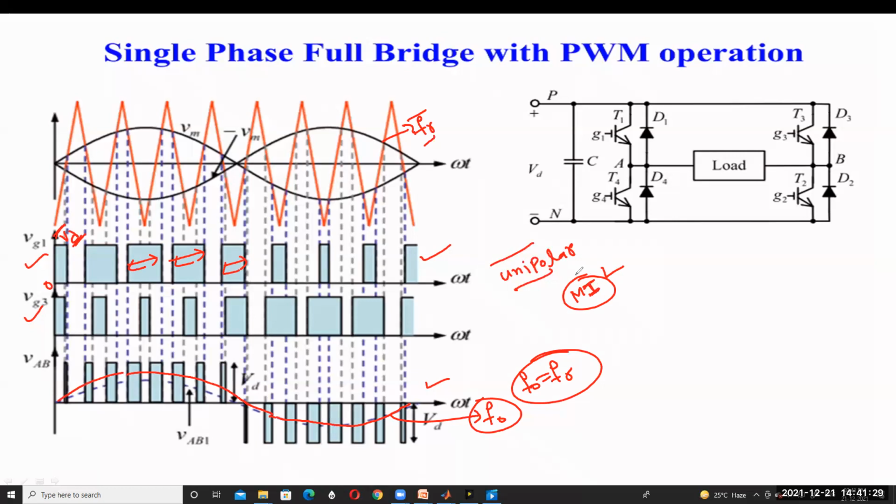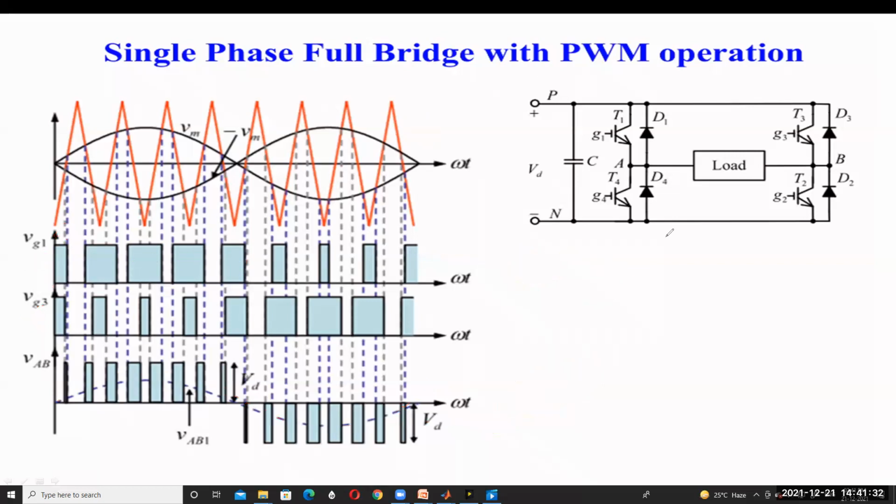So in this design of the inverter, we need one voltage source, VDC. Different types of components are required for designing the inverter in MATLAB. First is the VDC, then the MOSFET, and next the load, for example a resistive load. Triggering pulses are required to give to the IGBT and MOSFET, so a pulse generator is also required.